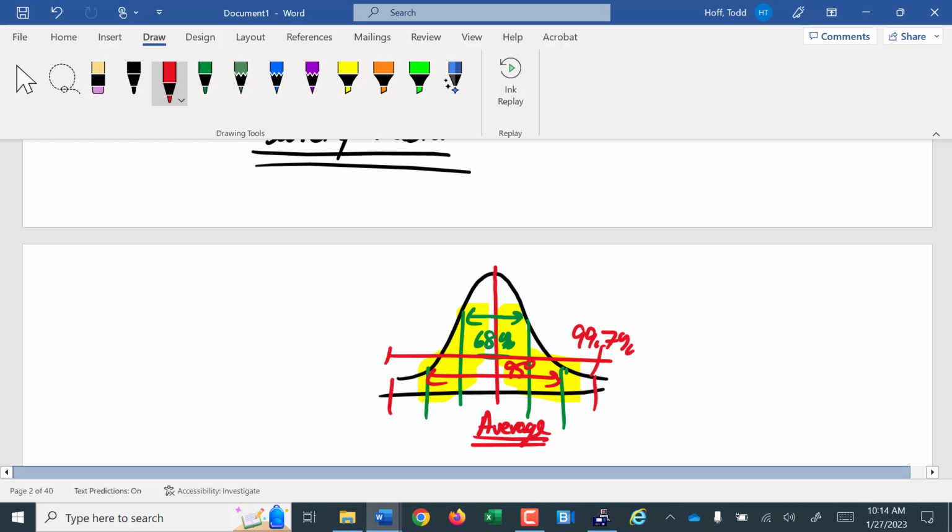The other thing is environmental conditions. Steel cables are very temperature sensitive. If you get into an elevated temperature, they get weak. Humidity affects the fibers of a fibrous rope. The fibers don't stick together as well. They can slide apart in high humidity. So those climate conditions can have a lot of effects.